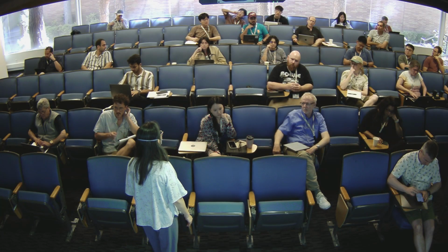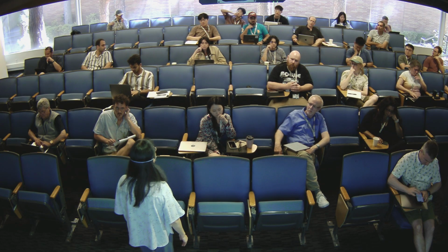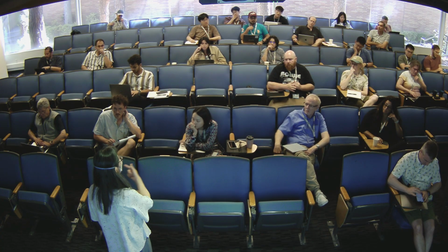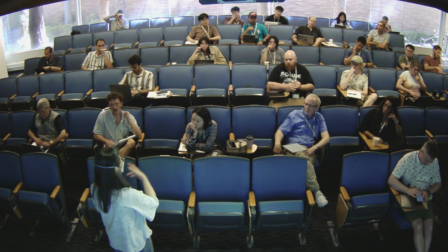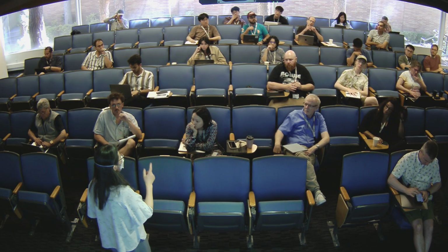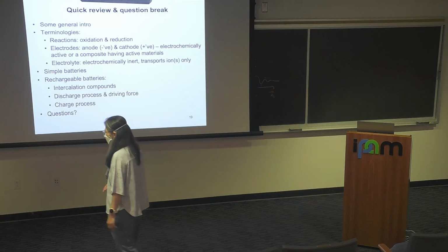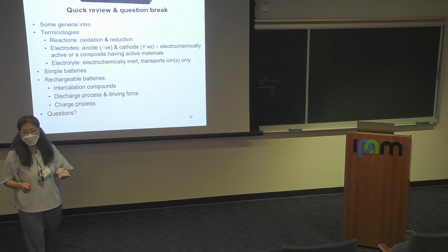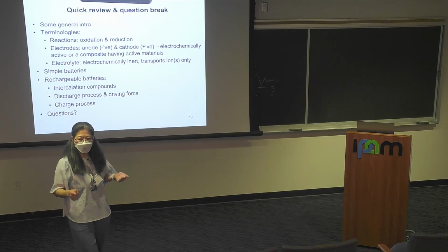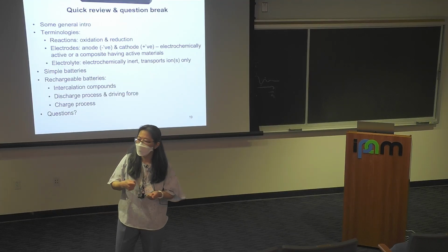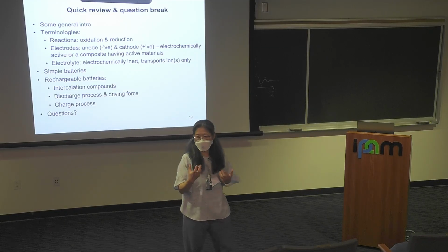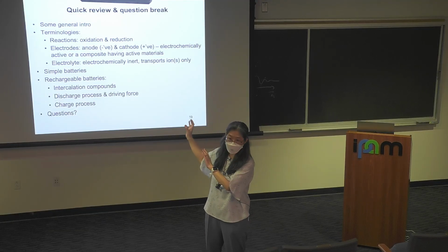If it's a high voltage battery, with high voltage batteries, you have to put a lot more voltage in order to recharge the system. And the problem is this. When you start putting in higher voltage, there are other material aspects you have to consider because they can destroy the battery. Electrolytes become unstable. There are going to be more side reactions. The material itself can start losing, those are oxides, right?